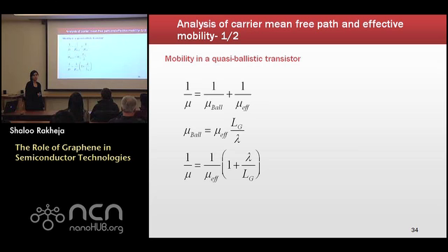Even for R0, I understand your point of how do you define an R0 for these devices if you're not seeing saturation. R0 for us is directly related to VXO, which is the injection velocity, which happens in saturation. If there is no saturation, how do we define R0? So we extract VXO, and from that we go back and say, okay, if VXO is this, this is what our R0 would be. And we hope that that is the R0.